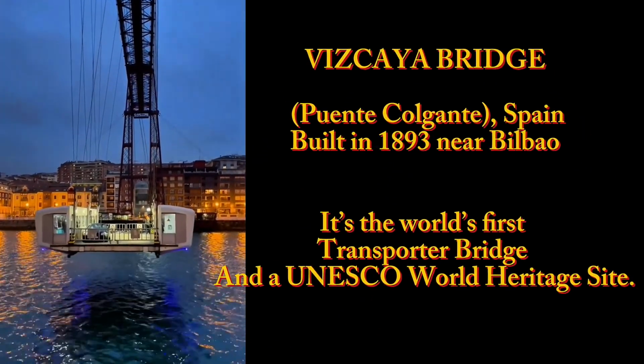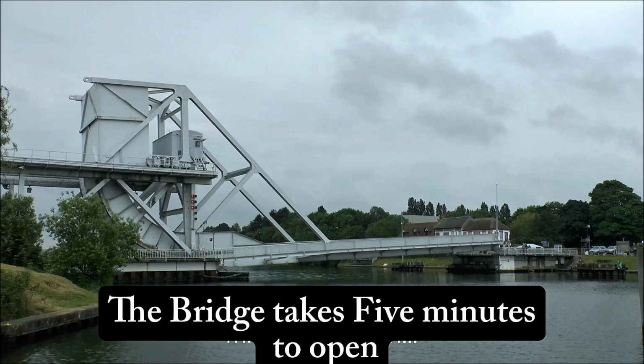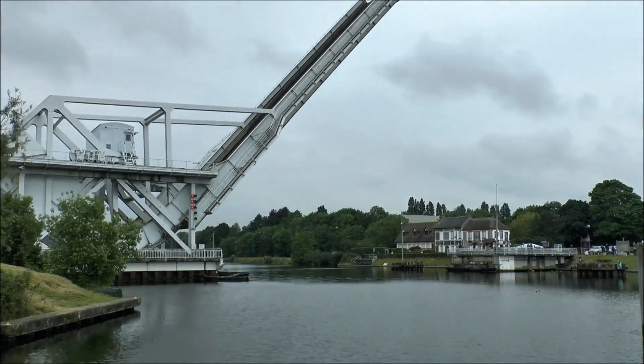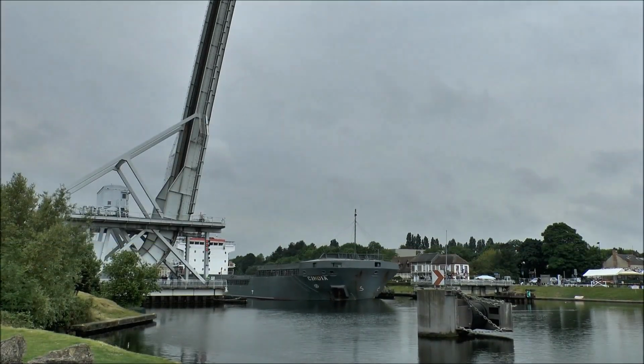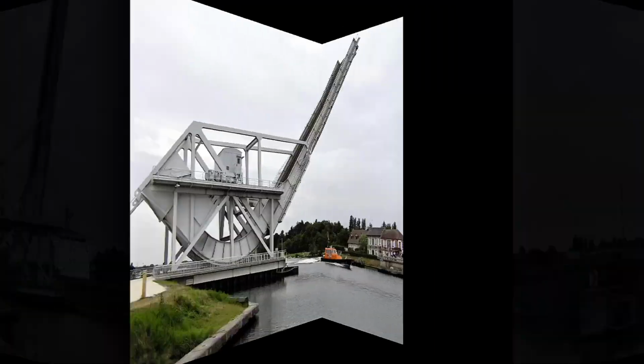Rolling bascule bridge. A rolling bascule bridge uses a segmental design where the deck rolls backward on a track as it lifts, rather than rotating on a fixed hinge. This rolling motion reduces the space needed for counterweights and machinery. An example is the Pegasus Bridge in Normandy, France.